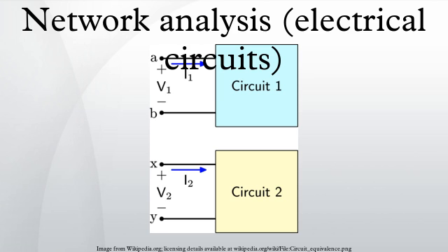In network analysis, rather than use the differential equations directly, it is usual practice to carry out a Laplace transform on them first and then express the result in terms of the Laplace parameter s, which in general is complex. This is described as working in the s domain. Working with the equations directly would be described as working in the time domain because the results would be expressed as time-varying quantities. The Laplace transform is the mathematical method of transforming between the s domain and the t domain. This approach is standard in control theory and is useful for determining stability of a system, for instance, in an amplifier with feedback.